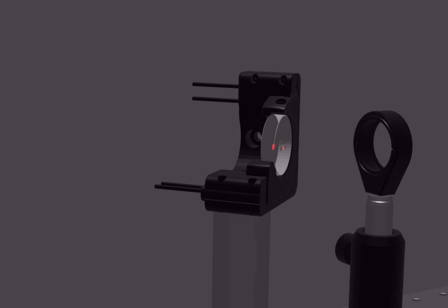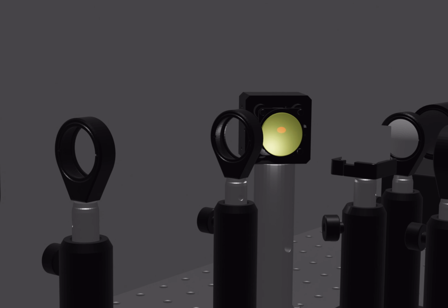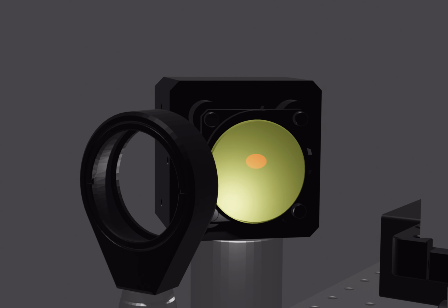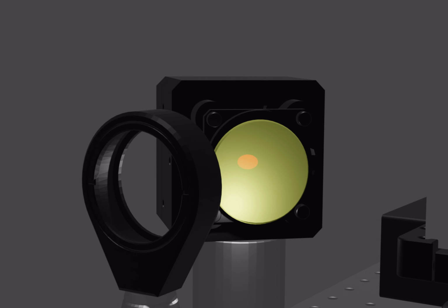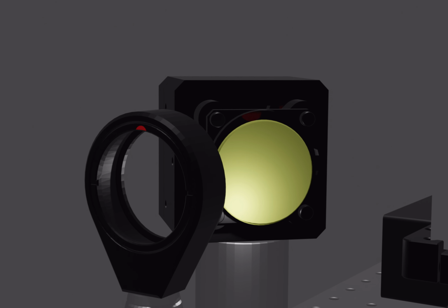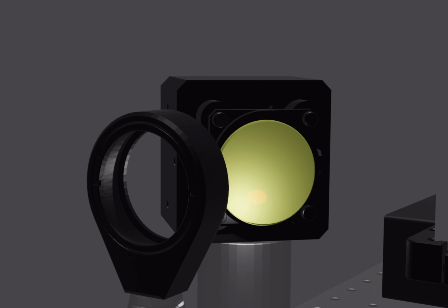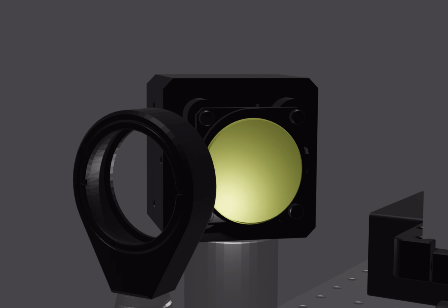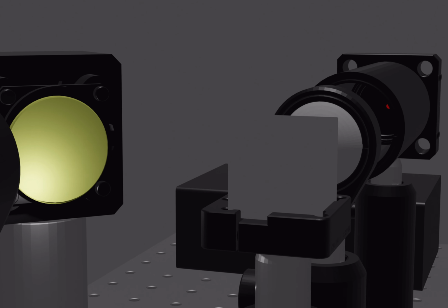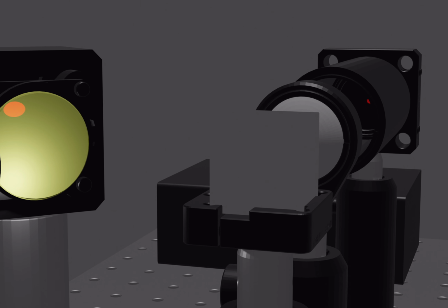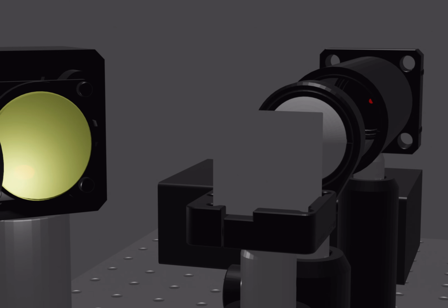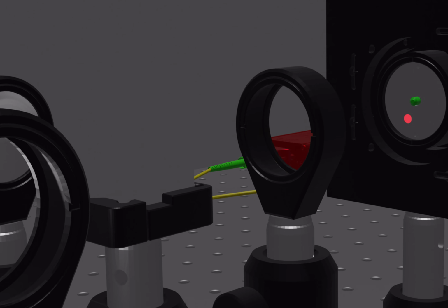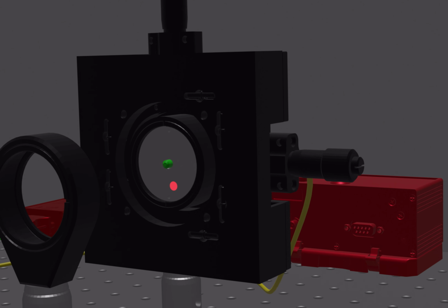Moving into the laser fine tracking system, the beam encounters a fast steering mirror, which is responsible for stabilizing the beam, thereby correcting the error imparted on the system. For this part of the demonstration, beam steering is disabled in order to help visualize how the error is impacting the beam's trajectory. After the beam reaches the fast steering mirror, it is passed through a beam splitter, which directs 30% of the light to a quad cell detector located behind the beam splitter and 70% of the light to an optical fiber located right of the beam splitter.